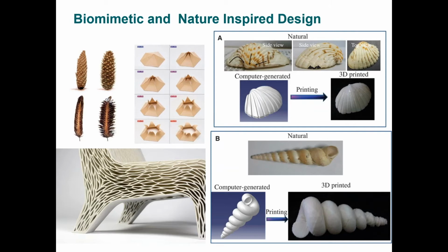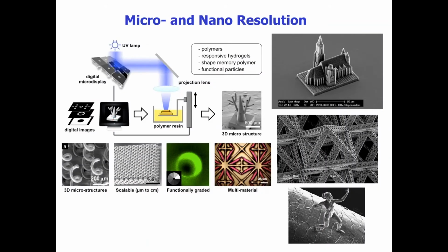However, my first introduction to 3D printing actually started 20 years ago when I heard about stereolithography. SLA actually is a newer term, but in the past, stereolithography and two-photon polymerization have been used to produce interesting objects in the microscale. As shown here, the effective use of light and a resin material that includes monomers, initiators and cross-linkers allows light to be directed stereolithographically to produce objects in the micron to centimeter scale. And this is all digitally processed based on movement, let's say, of micro lenses or elements of DLP, or digital light projection.